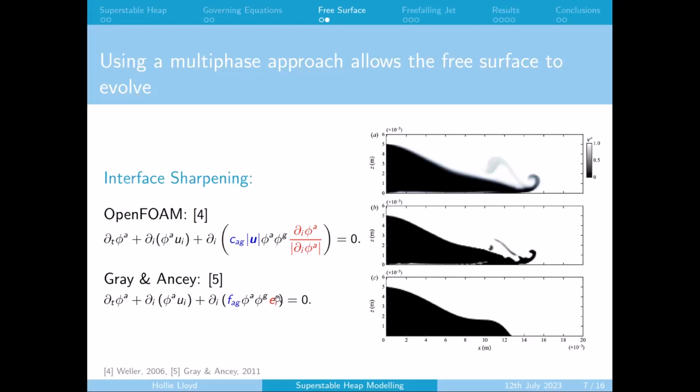But what it means is we have free choice of the direction that we choose to force our material in. So we can choose a direction which both compresses the interface as well as evacuates bubbles. So you can see that in this bottom figure here where this is implemented. You can see that we still have this really sharp interface because in this instance, air is just being forced upwards and grains are just being forced downwards. So our interface is still compressed, but because air is now being forced